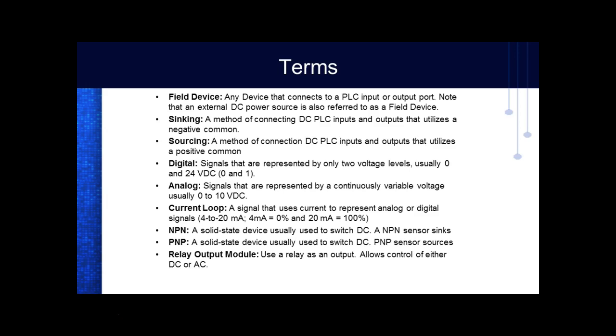Sinking, what's sinking? Sinking is put negative. Yeah, so sinking devices use a negative common. Sourcing devices use a positive common, right?